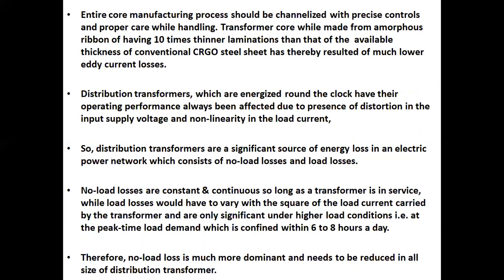Transformer core, while made from amorphous ribbon of having 10 times thinner laminations than that of the available thickness of conventional CRGO steel sheet, has thereby resulted of much lower eddy current losses.